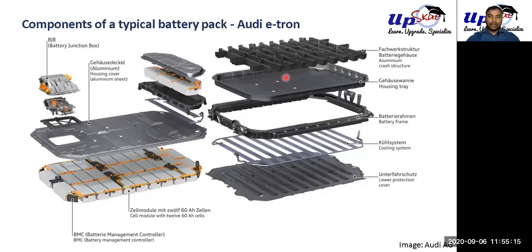Okay, so on the outside we have our cooling plates, and outside of that there is always a protection, because the road will have debris, right, rocks and all, so this thing protects the cooling plate. On the inside, this particular design has a crash structure. It is also called a reinforcement structure. This cross shaped design actually provides strength for both frontal collision and sidewise collision, because it has both longitudinal and cross members.